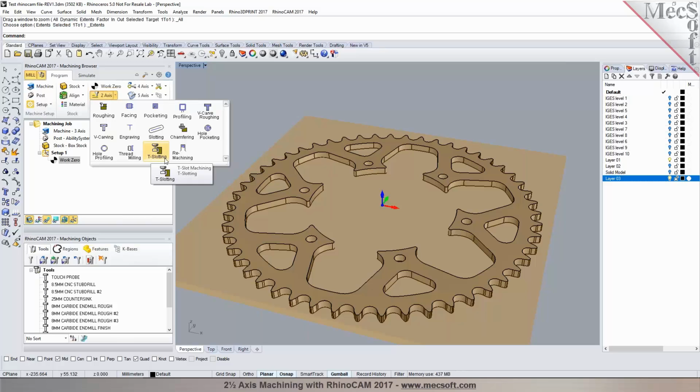Now in our Pro and Premium configurations, we also offer remachining, which is like rest machining. So if you profiled it or pocketed with a larger diameter tool, you could go back and machine with a smaller tool, so it knows the material that's being left from the previous step.